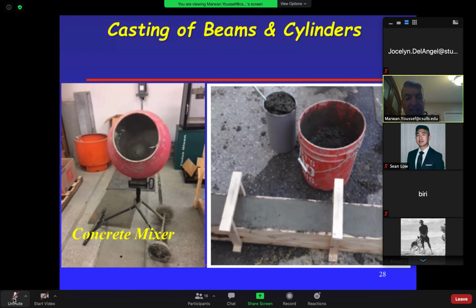If they have to wait, exaggerated, 3 hours, the concrete is no longer good. Usually the job specification will tell you how long the concrete truck can wait before emptying the product, because the longer he waits, the worse it is.